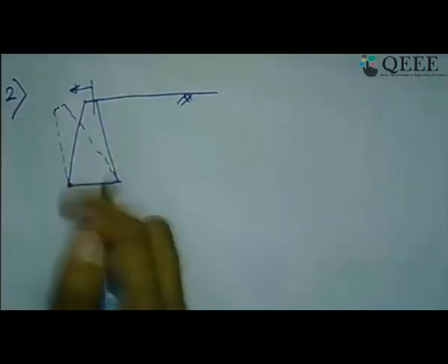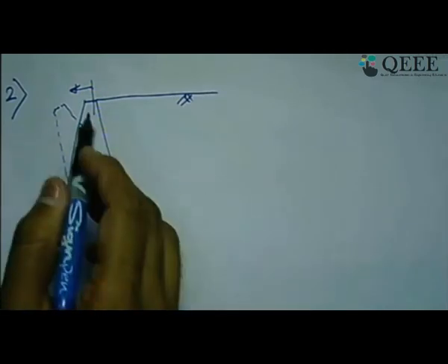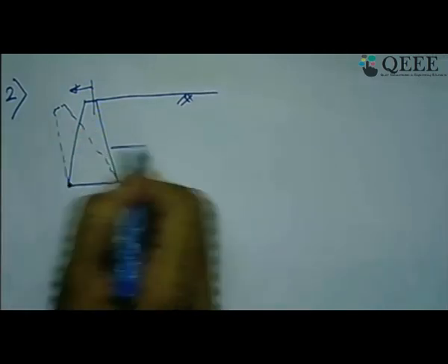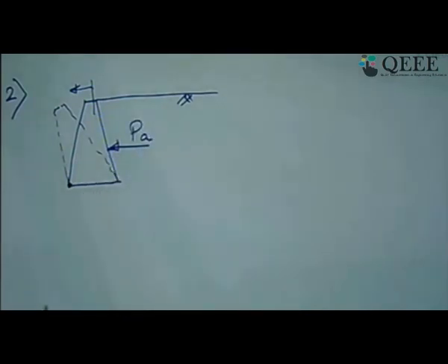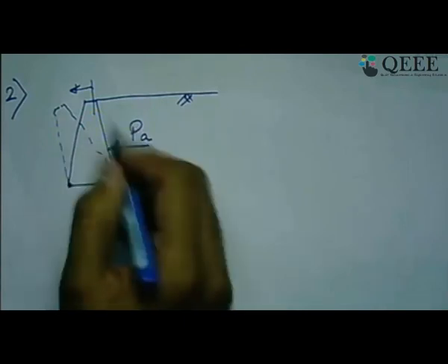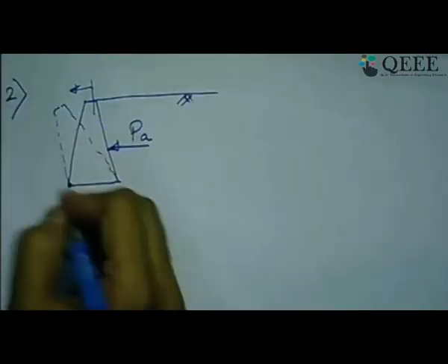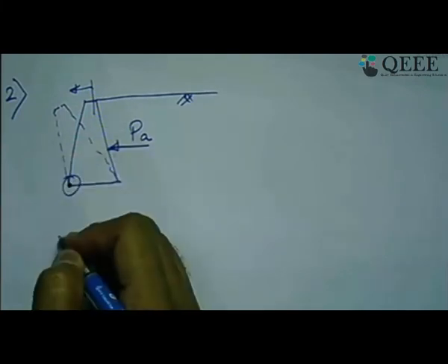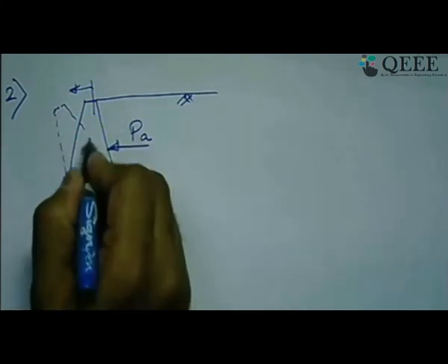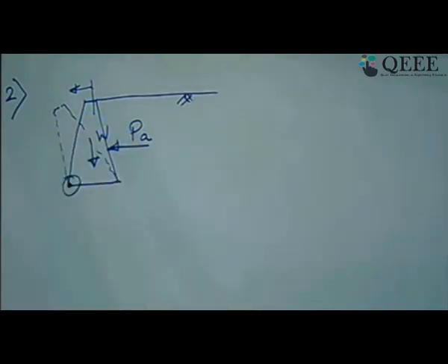So that rotation also we have to find out the stability of the wall. And why this happens? Because here again your main contributing or disturbing factor for this overturning to take place is nothing but your earth pressure, lateral earth pressure. Because of this pressure, wall tends to rotate about this point. So when it is trying to rotate about this point, who gives the stability? Again, your weight of the wall, what you are going to design, that will give the stability.